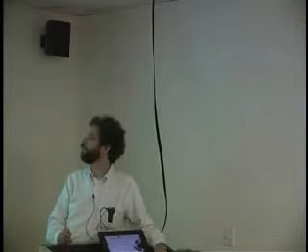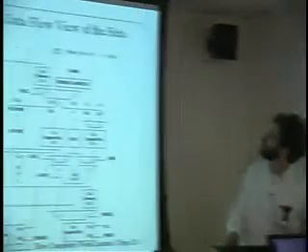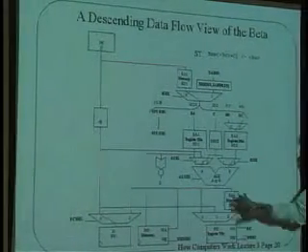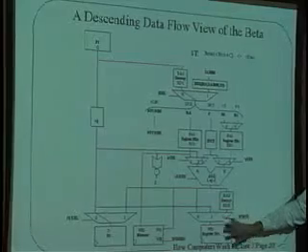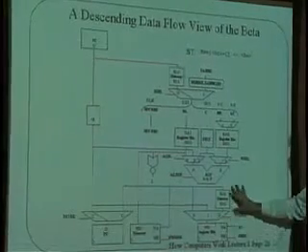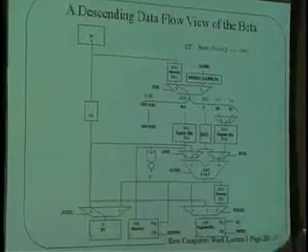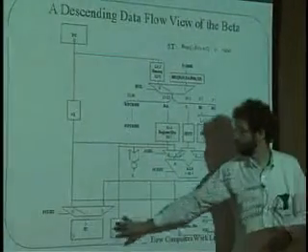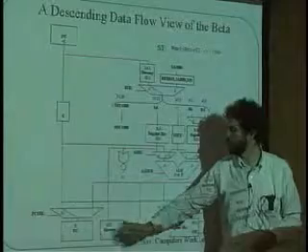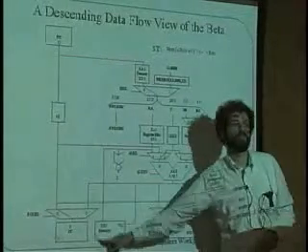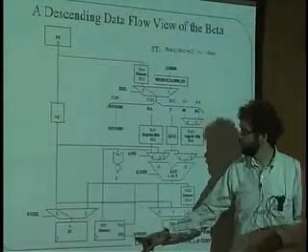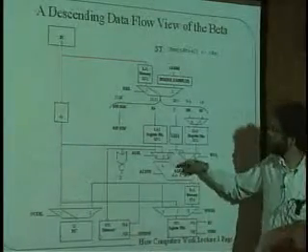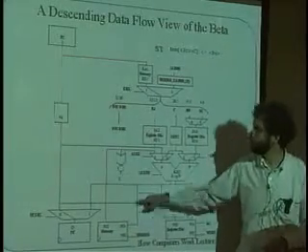Okay, load to store. Let's go back and forth. Here's a store. In a store, we're not going to be using the read stuff at all, and we're not going to write to the register file at all, so you'll notice this is all dark. However, what we are going to do is we will use the write path of the slow memory, the big slow memory, and that's over here. And this is now being turned on for the first time. So WEMEM is now on.